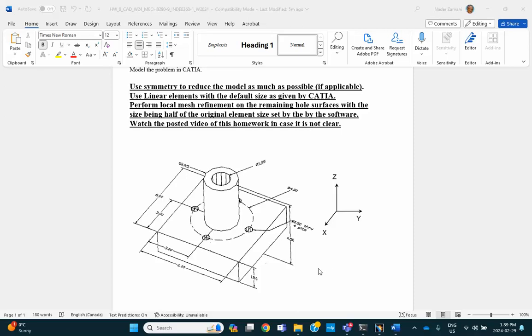But as a matter of fact, that is not the smallest portion. If you take 1/8 of this model, and you repeat it 8 times around it, you basically have the knowledge of the entire stress distribution and displacement of the structure.